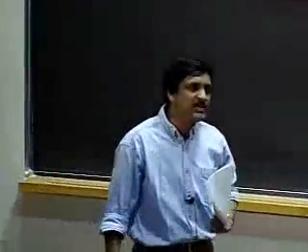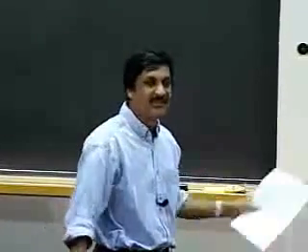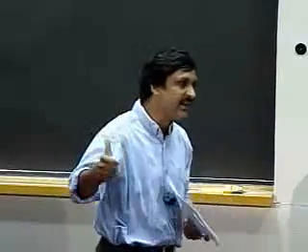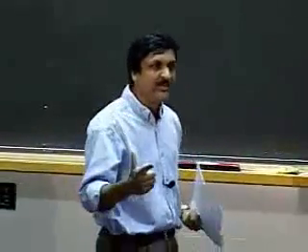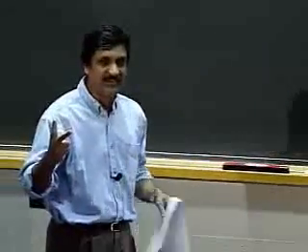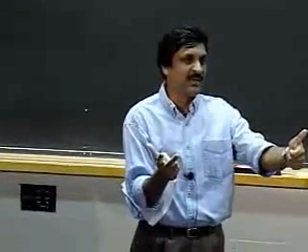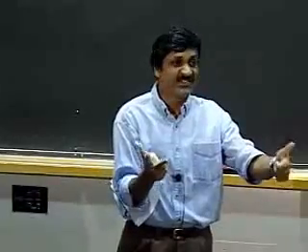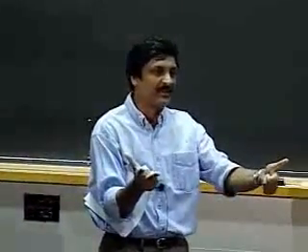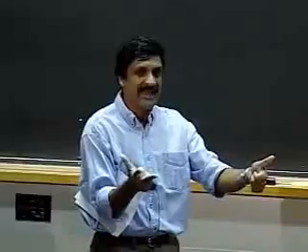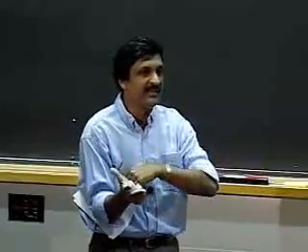Again, as I pointed out at the beginning of this lecture, no new foundations today, no new theories, no new disciplines, no new laws. We're just going to take what we've learned: three simple things, infinite gain, infinite input resistance, zero output resistance, plus this new thing, V plus equals V minus. Just armed with those four principles, we're going to charge ahead and analyze a bunch of circuits. It's a lecture on pure applications today.